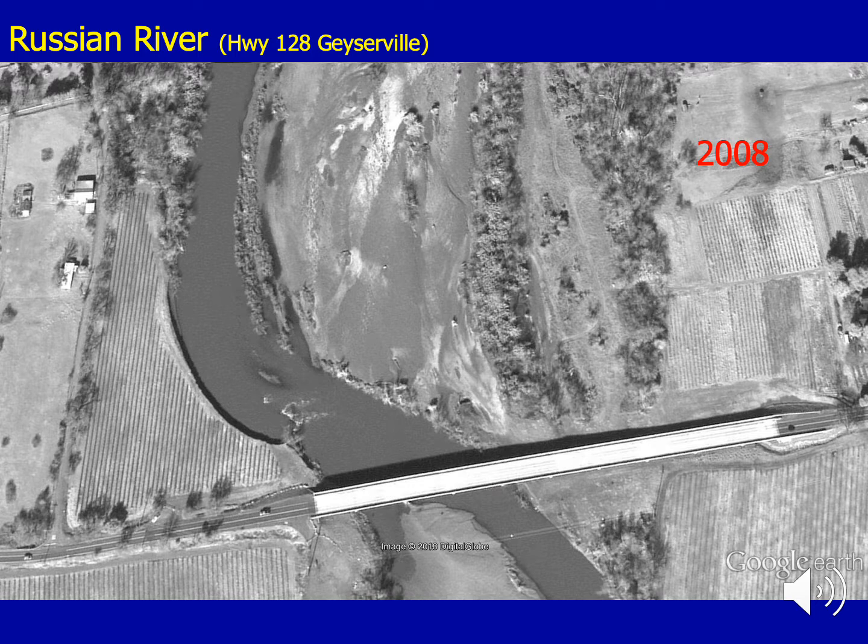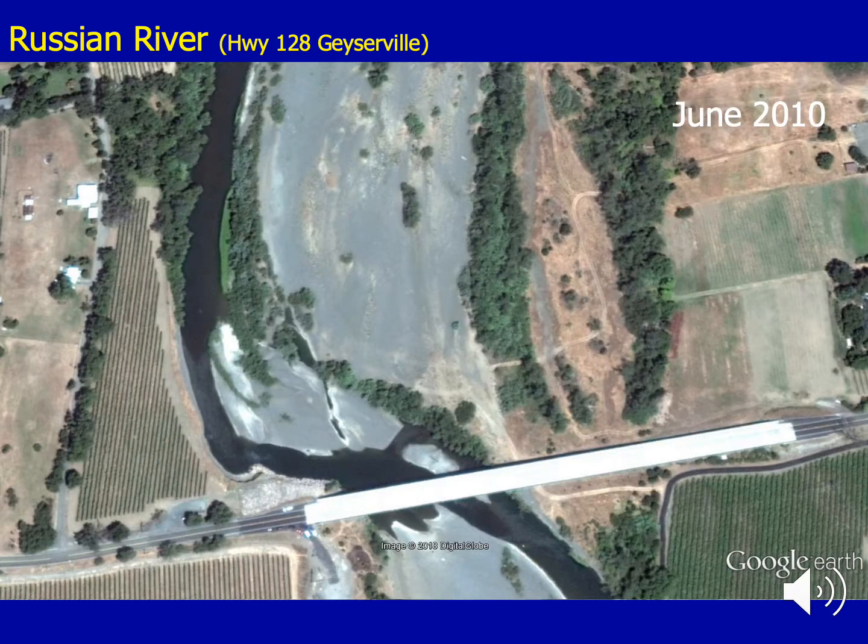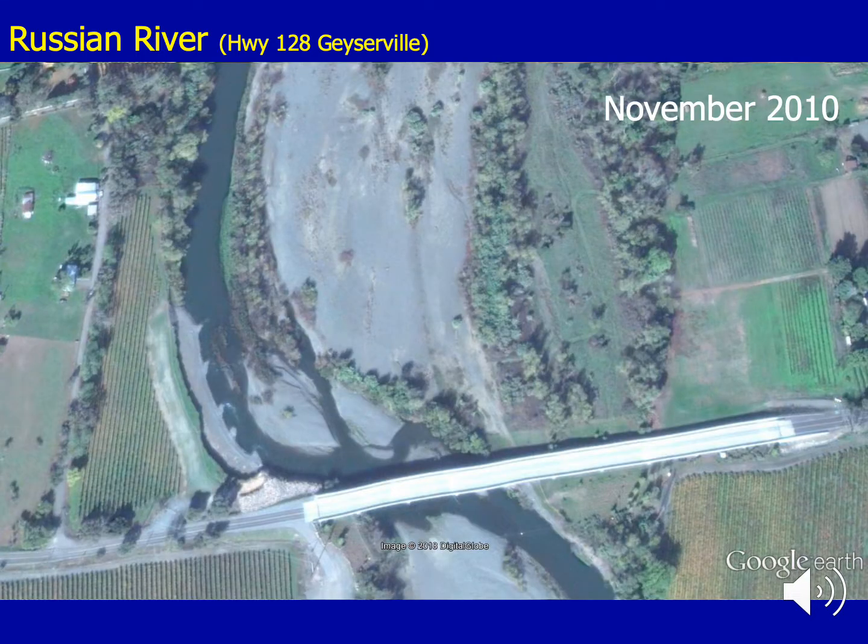2008, and this is a higher flow, but you can kind of get the sense here that we're starting to scour more this way. This abutment's starting to become compromised. 2010, first round of riprap goes in to try to save the abutment here. You can see the vineyard continuing to go away. Again in 2010, at this point, the erosion is sort of declared mission critical here with the scour behind there as well as here. So another multi-million-dollar emergency repair happens now.